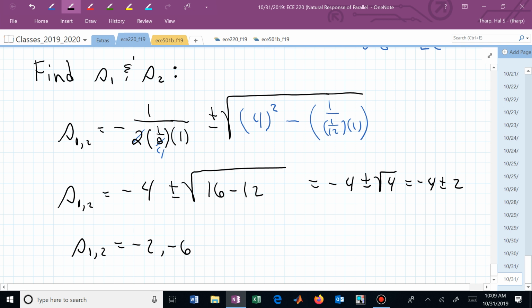What case are we in? Are we in the underdamped, purely oscillatory, overdamped, or critically damped? Where are we living on the complex S-plane with these x's? They're on the negative real axis, aren't they? And they're real unequal. This is now our overdamped scenario.